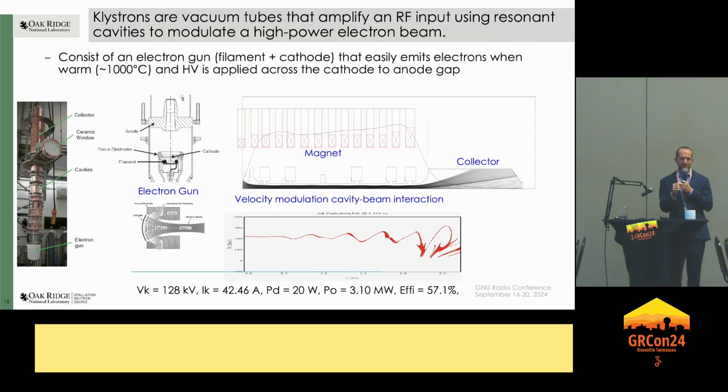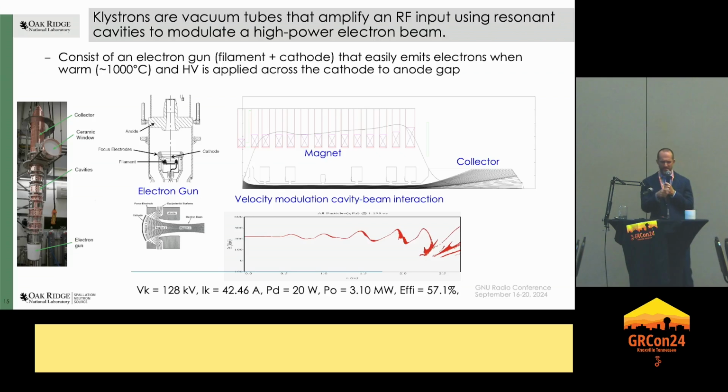That creates that beam. And you can see there's a picture there of a klystron halved and laid on its side, right? So in the first cavity, we tickle in a little bitty RF signal. It's usually on resonance. And then that starts bunching the beam. And as those beam bunches pass the subsequent cavities, they actually induce, or couple rather, a wall current that mirrors the actual pulses as they go by. That wall current then sets up a voltage across the gap. We talked about gaps earlier. That acts on the subsequent electrons and makes the bunching even more intense.